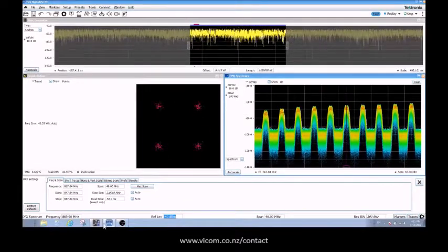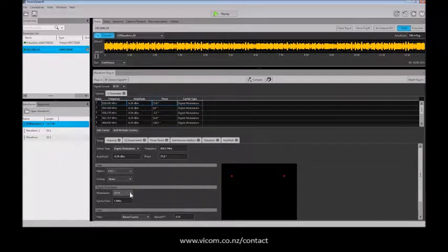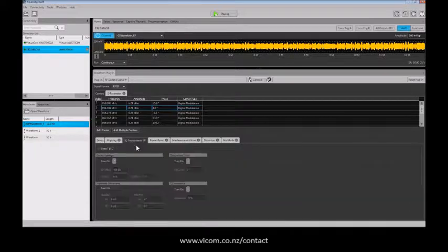So I'm going to go back to the software controlling my RF generator or my arbitrary waveform generator, SourceXpress. I'm going to add something to this. So we have this number 1 here, the 868 megahertz. Let's make this QAM16. That's it. And let's make number 2 here. We add some impairments. And we can turn on IQ imbalance. Let's put it at 10%.